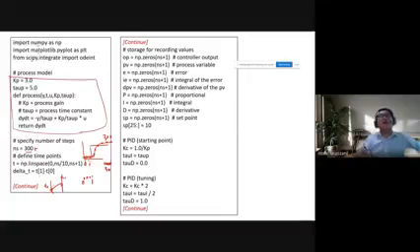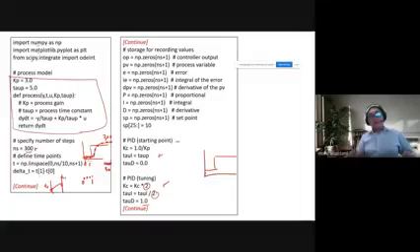After that, this is just storing properties, like the earlier one I mentioned. It's just temporary storage, and then they will be overridden after it goes into the loop. And then this is the declaration, so declare for KP, KC, tau, and tau D. And then these are the tuning values, say you have the value 2. Later, if you want to make sure the response is fast or sluggish, you can just tune from here and assign the value accordingly.